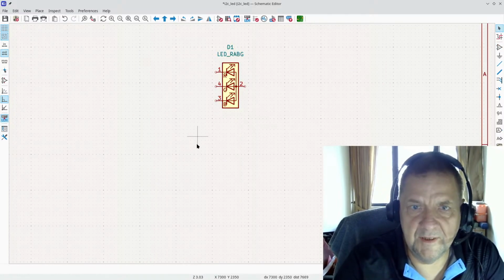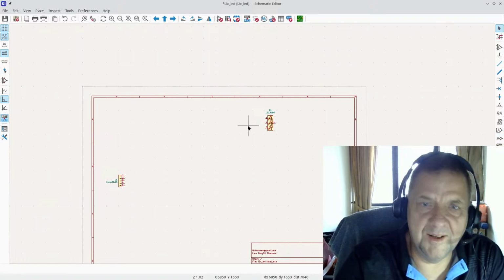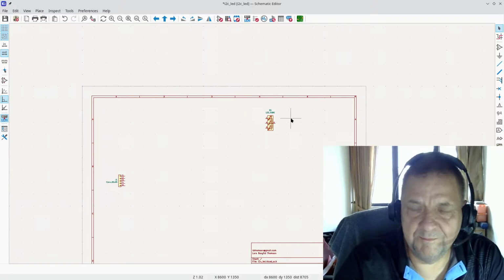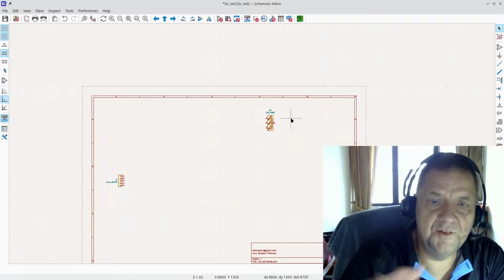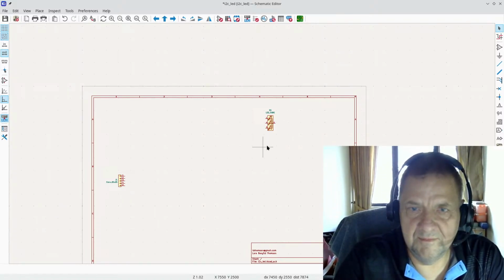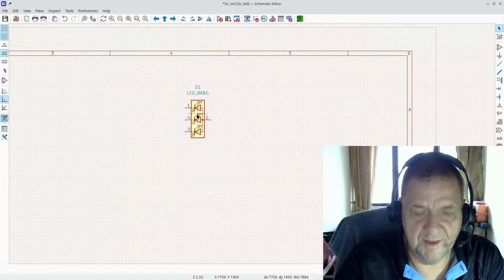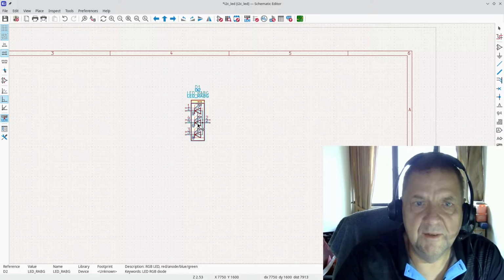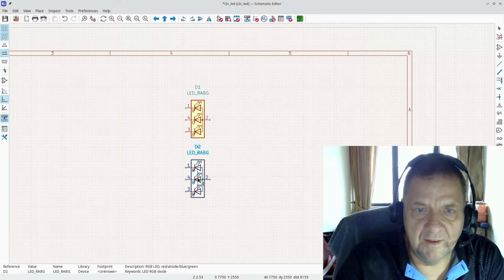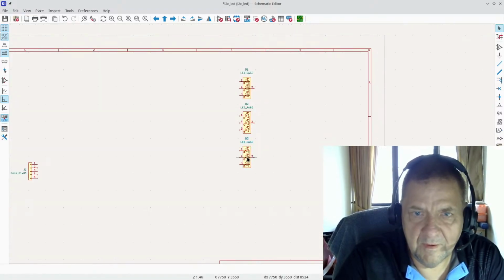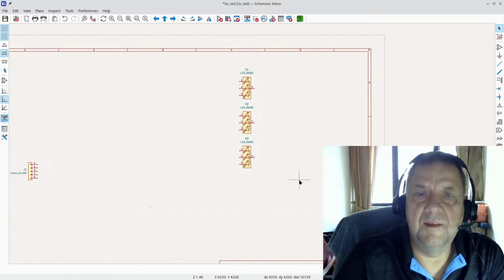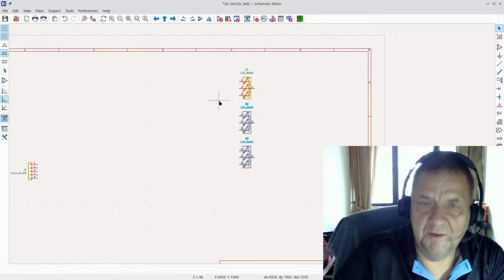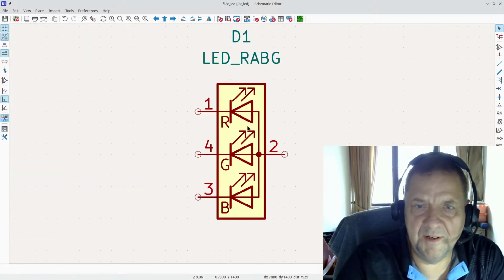This is a little hard to show, but one of the things about KiCAD is you really need to use the hotkeys. So I need to get used to explaining the hotkeys in this video. Now I have put this in, I can press Ctrl D for duplicate, and I can duplicate this one to another one. I can duplicate it again. And that was stupid. I'll get back to explaining why. It is better to have it completely configured first.